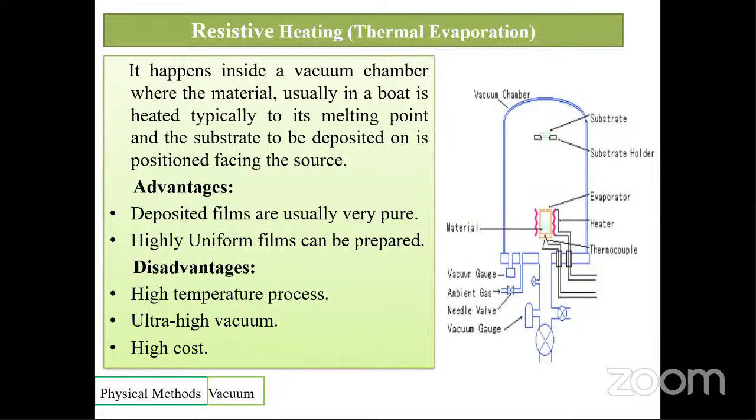And all of us know why a vacuum is required, because otherwise what will happen in that case? The atoms which will be evaporated will not reach the substrate, because the mean free path will be less, as these molecules or atoms will collide with the atmospheric gases and all those things. So that's why we need a vacuum here.